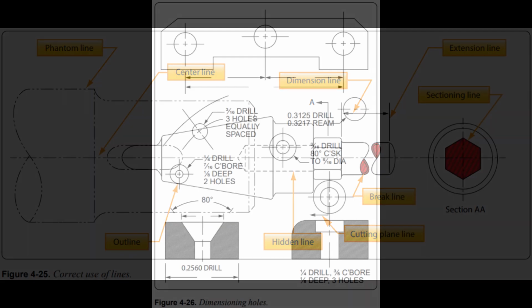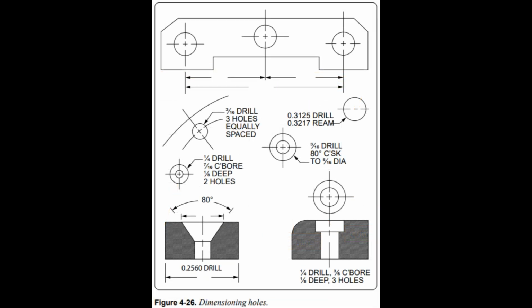Dimension lines. A dimension line is a light solid line, broken at the midpoint for insertion of measurement indications, and having opposite pointing arrowheads at each end to show origin and termination of a measurement. They are generally parallel to the line that the dimension is given for, placed outside the outline of the object, and between views if more than one view is shown. All dimensions and lettering are placed so that they read from left to right.